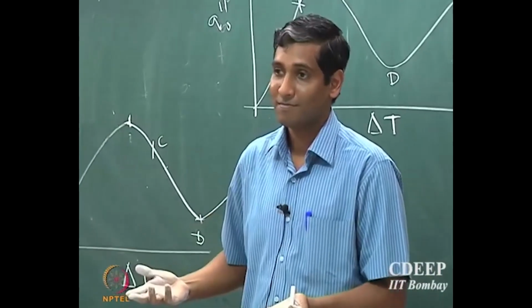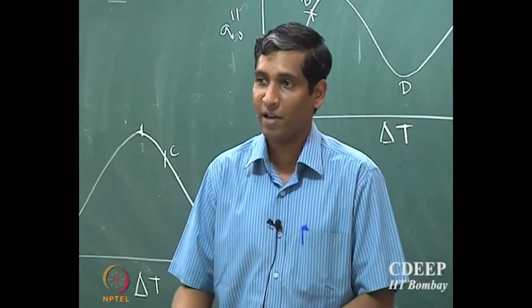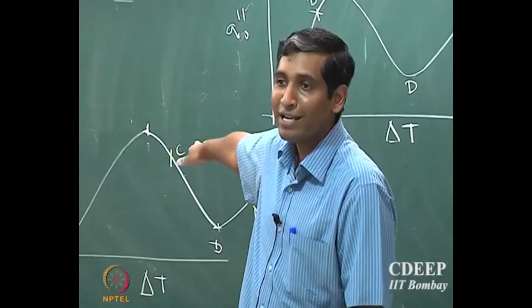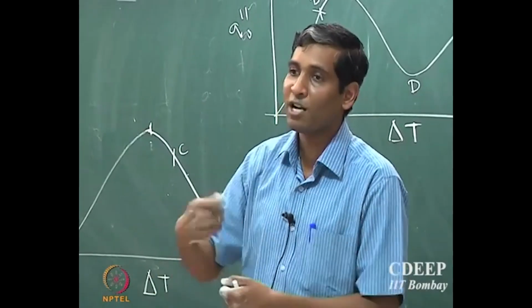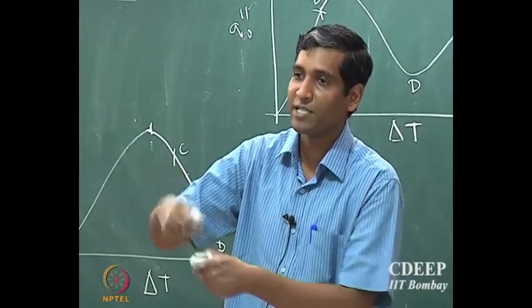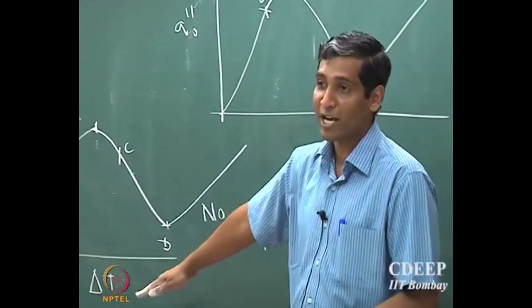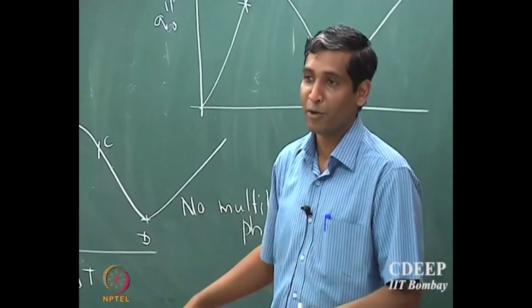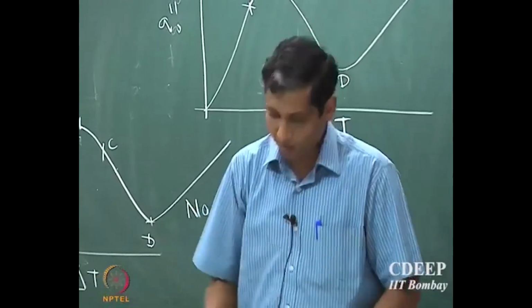So that's a problem. Until all the fluid is heated and converted into vapor phase, the fluid will continue to be at Tsat temperature. Only the local vapor temperature will go above Tsat, but the vapor is going to escape and go away. So the liquid continues to be at Tsat temperature. They will continue to be at the boiling point till all the liquid escapes into the vapor phase.